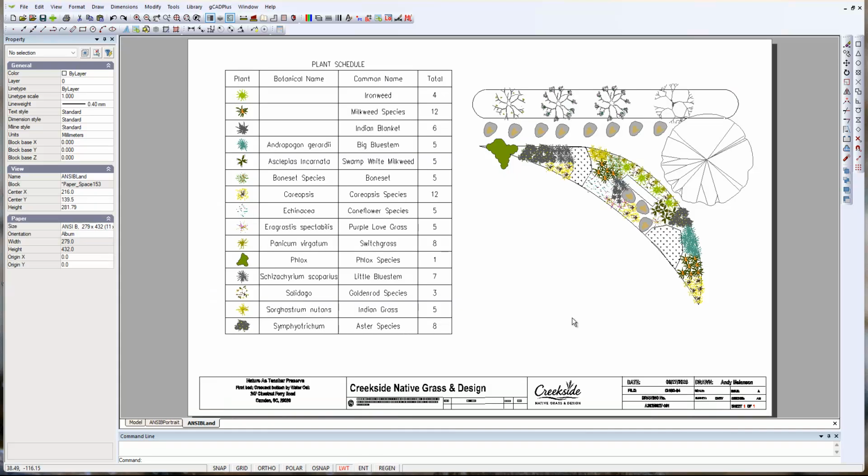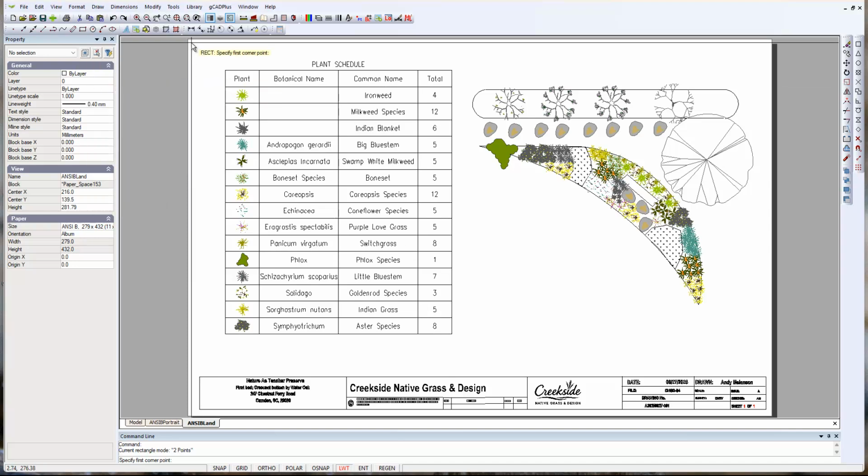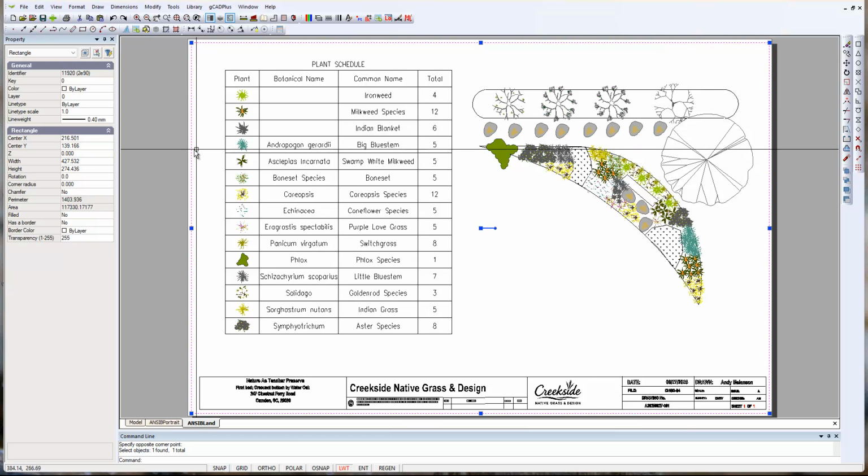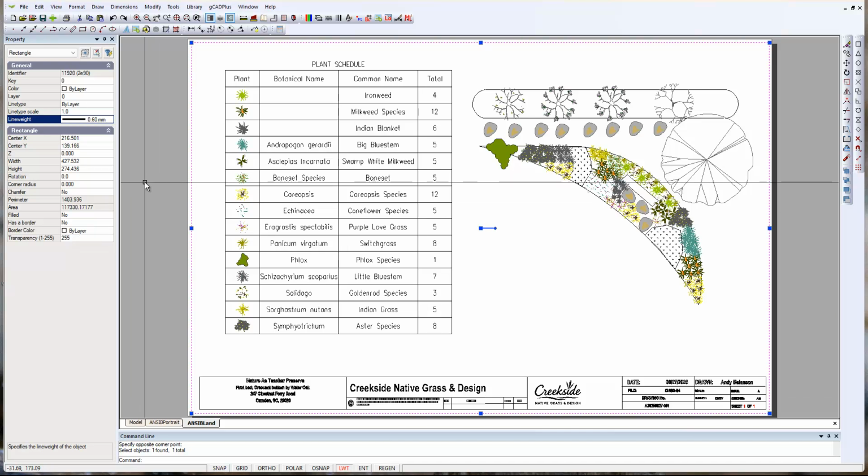The reason I want to go back there is that earlier you may recall that our designer wanted to have a bold line around the outside. That's effectively drawn with a 2-point rectangle, and we can pop it in like so, and then it's on layer 0, we can set its line weight to 0.4, or for emphasis just at the moment we'll pump it up to say 0.6 so that you can see what we're doing.